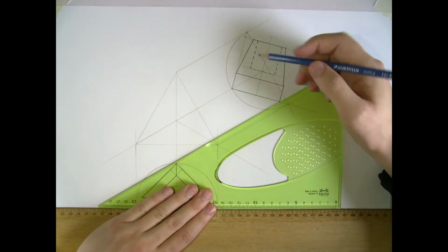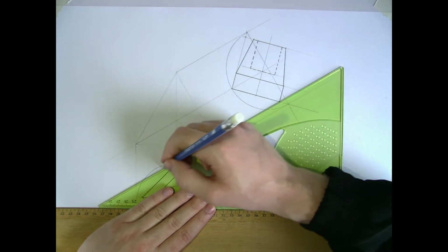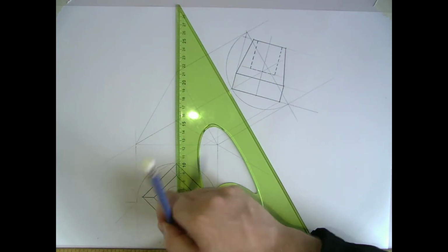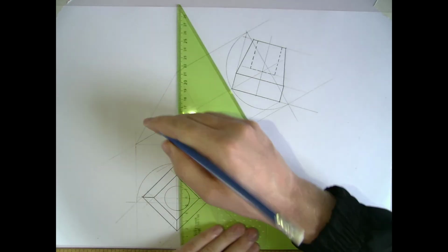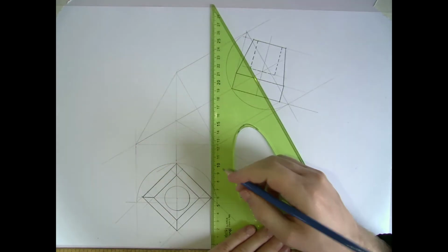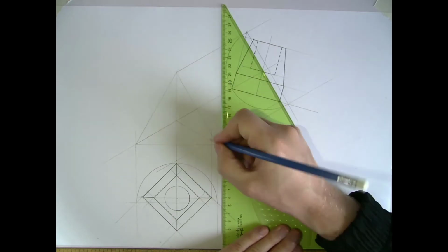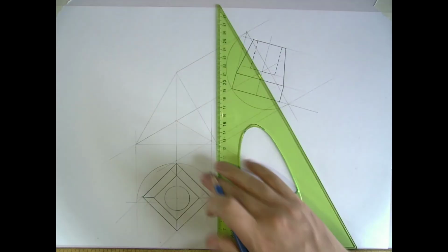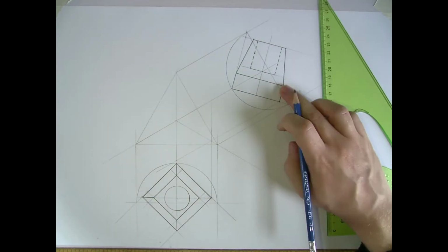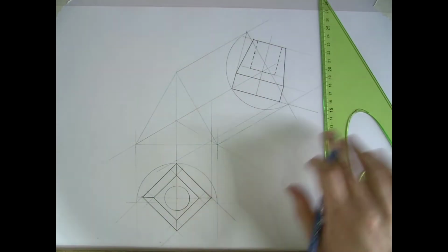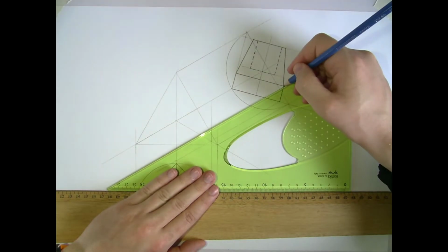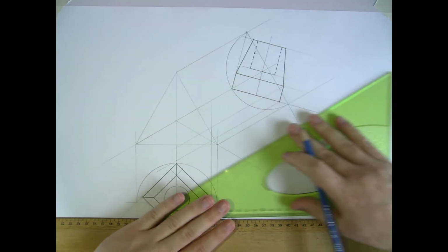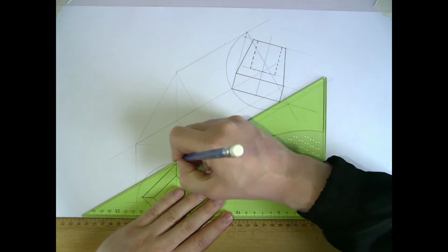So start by projecting lines down and in. I'm going to find that side of it now up in elevation. So that gives me that point here, and this one is here, which is where it crosses that point on the axis anyway. If I find the top of that, so up to 20 millimeters, that's also going to be in line with that same edge. So I just need a second line to come down from there. And I now have this face of it here complete, so I can darken that much of it in.